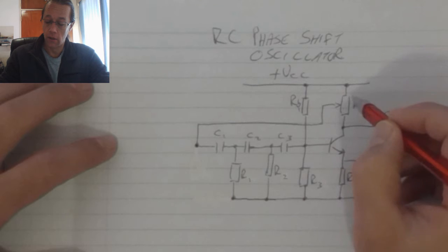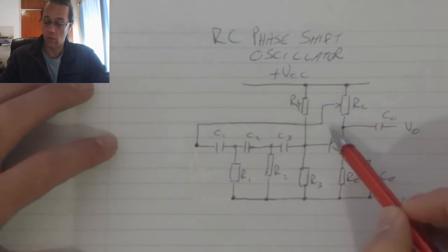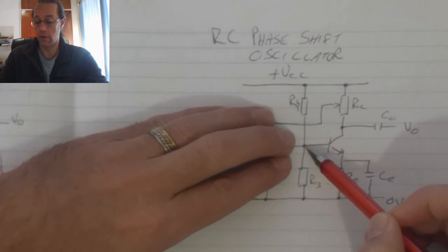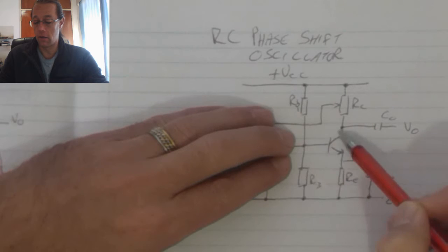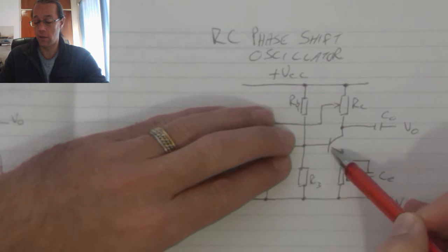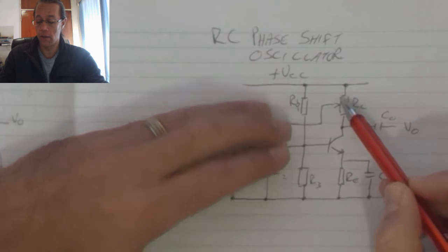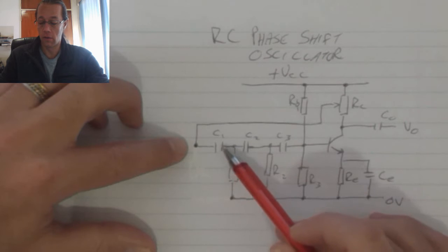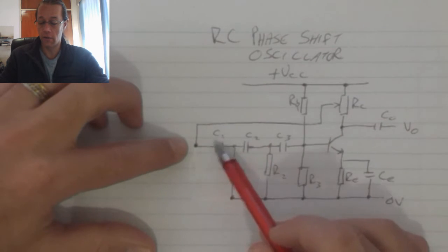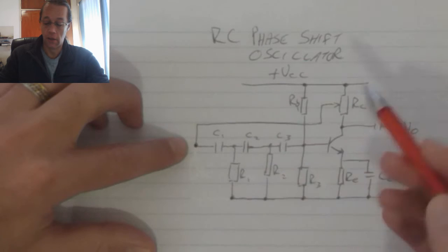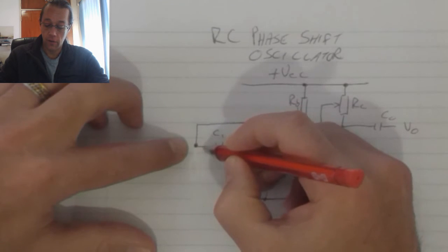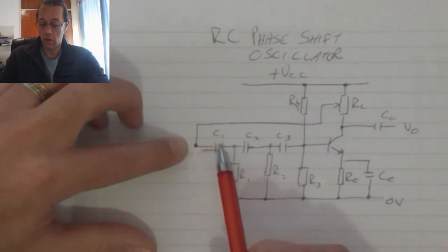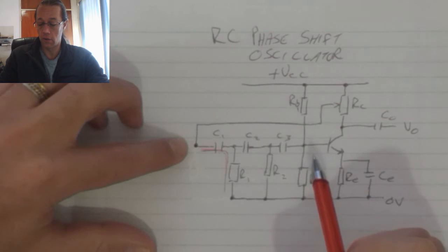If we look at this configuration, when we connect the transistor onto the base voltage divider biasing, the transistor is going to activate. That is going to allow a feedback signal to be fed through RC, C1 and R1. So our first shift will occur across C1 and R1.